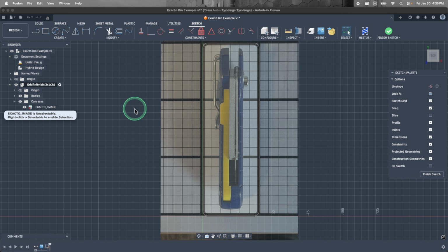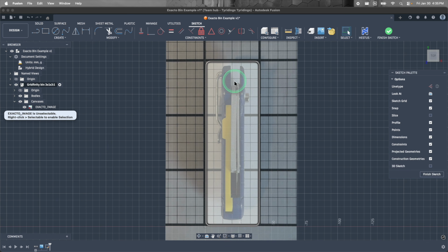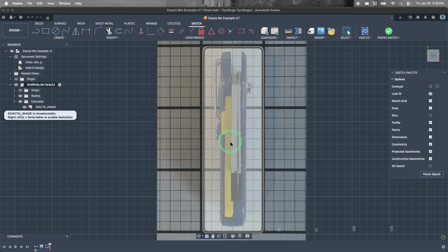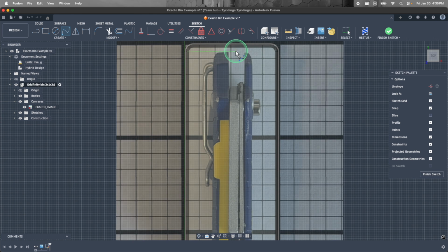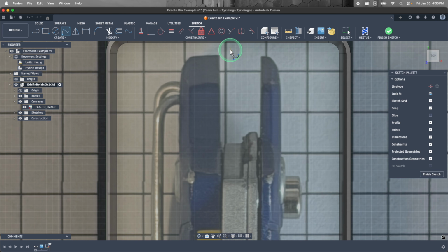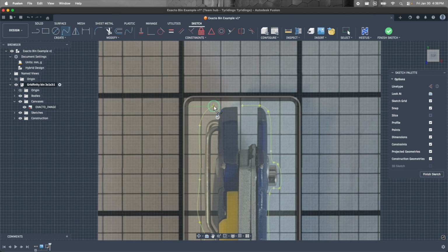can use your normal sketch tools to approximate the tool's perimeter for your extrude. With some tools, you can simply put in lines and arcs if the part is relatively straight. For me, I ended up using the spline tool since it offers the most flexibility to get more regular features. With the spline tool, just know that if you hit escape at any point while you're clicking through your spline points, it will erase everything you just splined together, which is a feature I've griped about before. So the safest method is to make sure you connect all your points to ensure the sketch is complete.